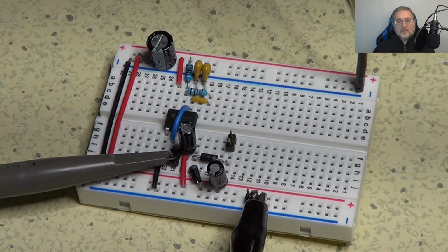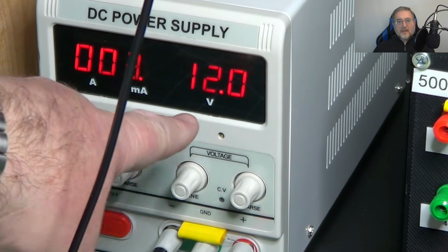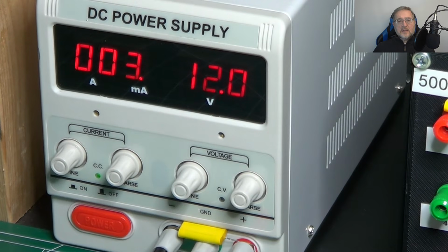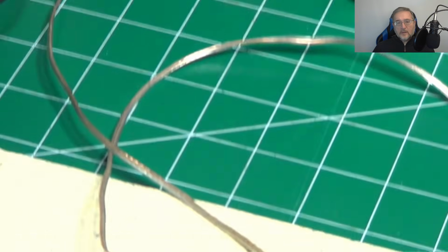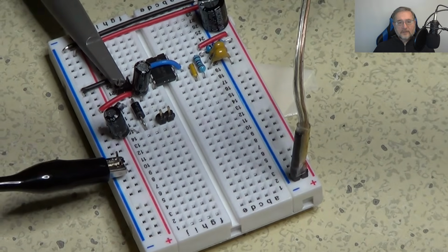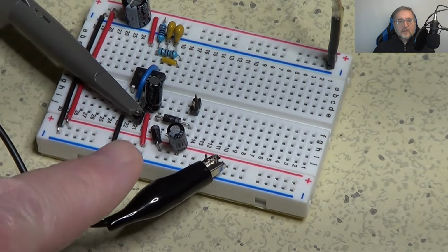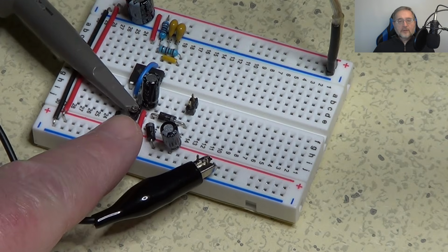The power supply is connected through this cable to my DC power supply, which is currently providing 12 volts. You can also see the current absorbed by the circuit, which is about 3 mA. This is in fact what is needed to keep the output voltage at the max value of 24 volts, while some energy is dissipated by the parasitic resistances of the circuit components and by the breadboard itself. In addition, I also connected the probe of the oscilloscope to the pin 3 of the 555, which will allow us to see the square wave piloting the voltage multiplier.